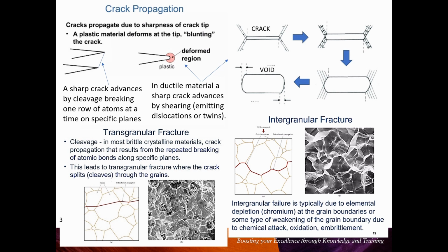And that's why body-centered cubic materials, which are more prone to non-ductile brittle failure, are typically not used in reactor cores. Although I understand some Gen 4 reactors potentially will use some ferritic steels in the core, but only at high temperatures, obviously.